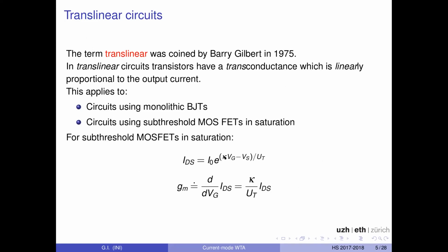That's just a property of the exponential. If in the exponent you have a sum of voltages and the sum adds up to 0, then you can break up the sum into products of individual terms: e to the VGS1 times e to the VGS2 times e to the VGS3.